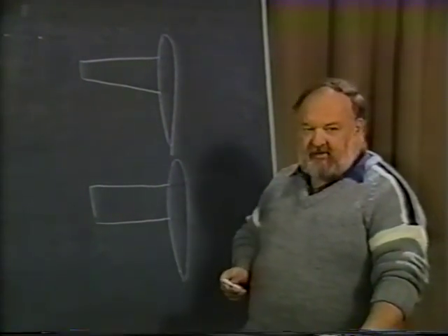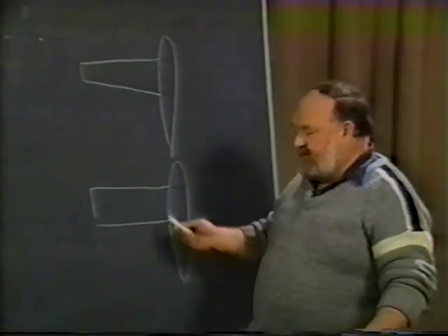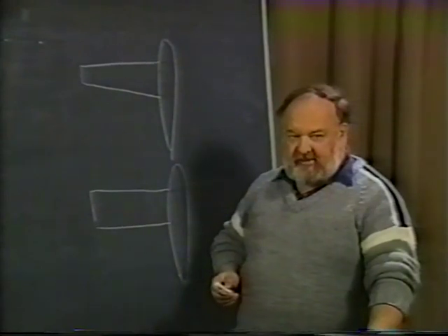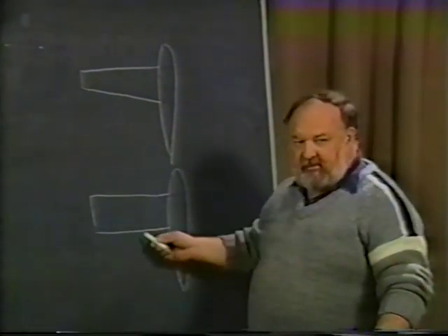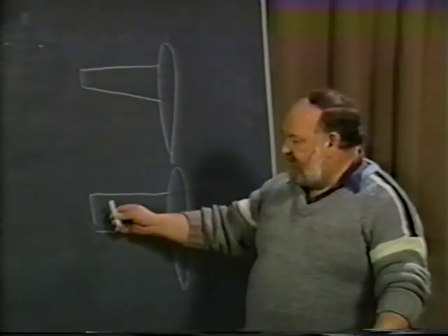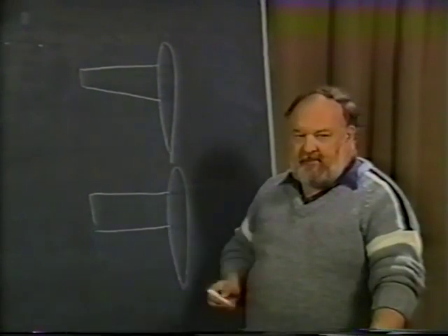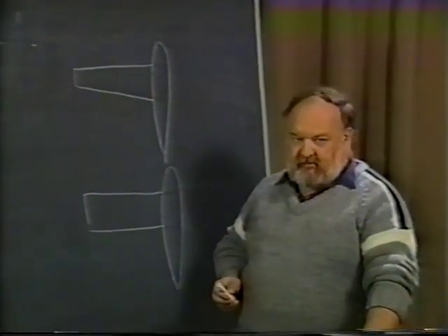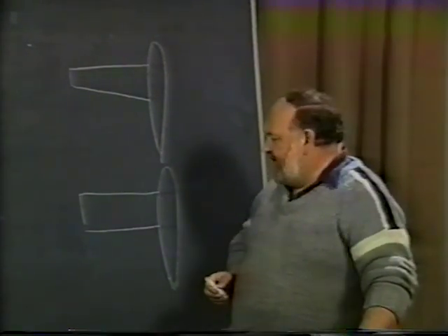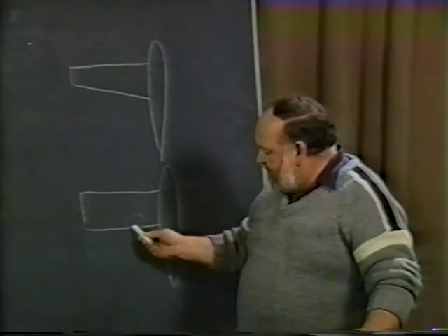The advantages are very definitely better, in the fact that the Reynolds number at the tip now remains the equivalent of what the Reynolds number is at the root. So one thing you know right off the bat is, without any twist in this wing or anything else, that the stall pattern of the particular wing itself will be essentially the same throughout. Now, what are the things we're really going to be looking for? Why is stall pattern so important, and what are the main objectives? Well, the ideal thing would be to have a stall pattern begin right in this region here.